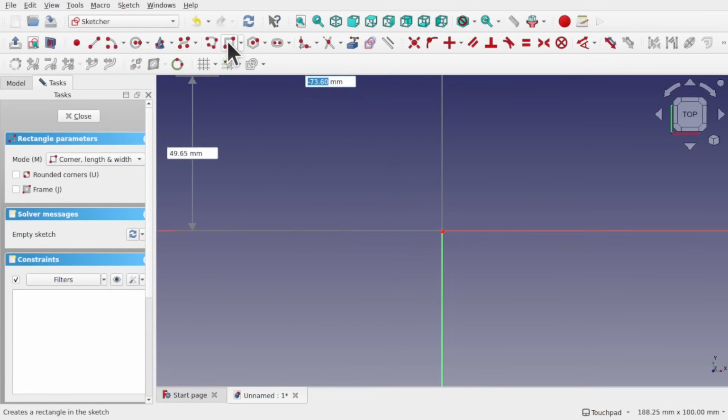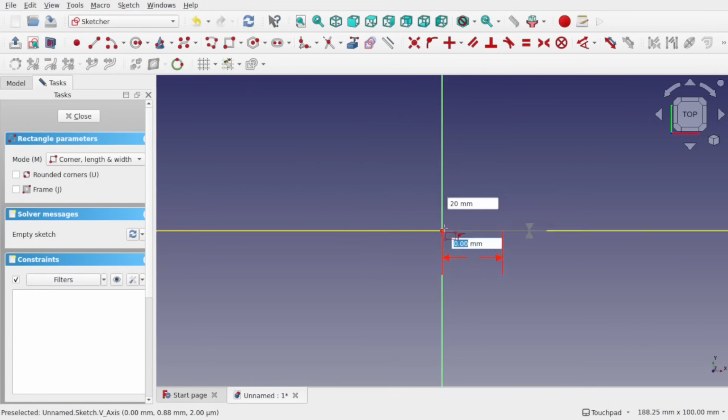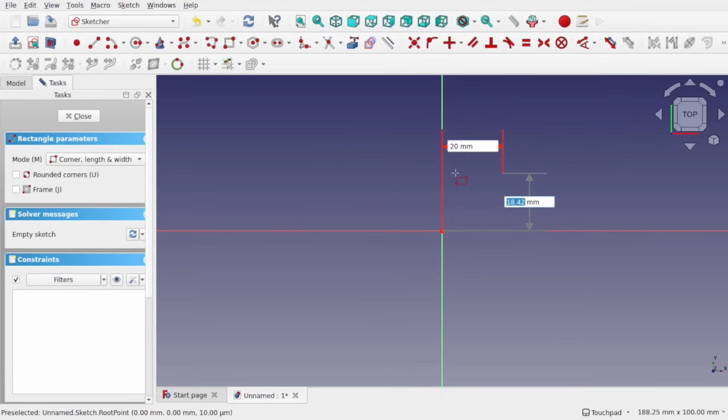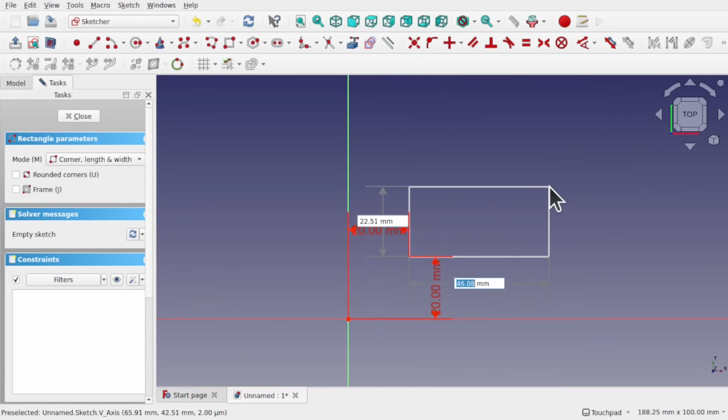So I've clicked on the rectangle tool, and you can see straight away we've got dimensions coming in without me actually clicking on the screen. So I can set this to 20, tab over, and it moves it and dimensions straight away to this center point. So go 20 and 20 and tab again, and now I start getting in this rectangle, which is the actual dimensions of the rectangle. So we've got position and dimensions with all. So let's tab, do 20, and let's do tab again for 40 and hit enter.